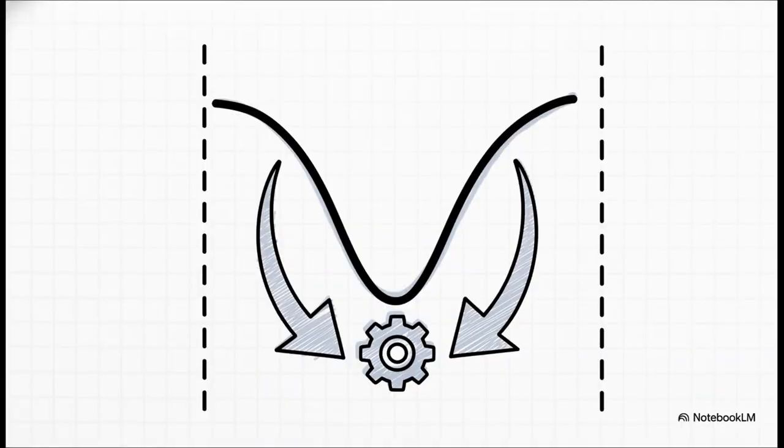Our new lower resonance omega 1 sits at 618 rad/s, and our upper resonance omega 2 is at 638 rad/s. So, as you can see, our steady operating speed of 628 rad/s is perfectly nestled safely in that zero amplitude valley right between the newly created asymptotes.